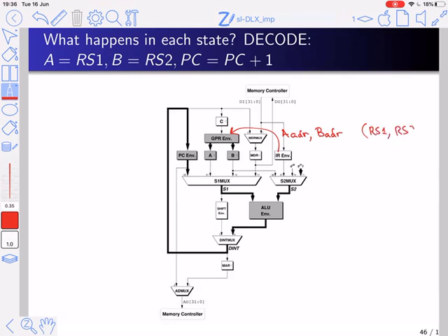Now, of course, you may say, but what happens if the instruction is not an R-type instruction, it's an I-type instruction? In that case, you're just reading something into B, which is gibberish. It's not of interest, but it doesn't cause any damage. Okay. So now the GPR reads the contents of one register given by this index and another register given by this index, and it stores them in A and B. This is how these 2 RTLs are executed.